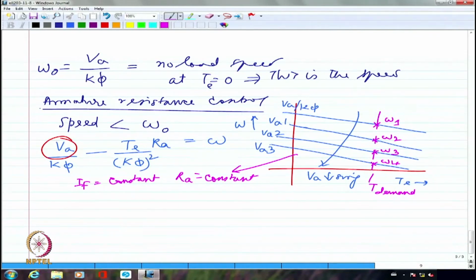So, this essentially tells me that the armature voltage control method is possible again for speeds less than rated speed, preferably. Because if I am talking about a motor rotating at 1500 RPM with a 220 volt supply normally, under normal operating conditions with rated excitation and so on and so forth, if I want to achieve a speed greater than 1500 RPM, that means I have to go for a voltage which will be higher than this normal rated voltage. Only then I will be able to achieve a speed which is greater than the nominal rated speed.